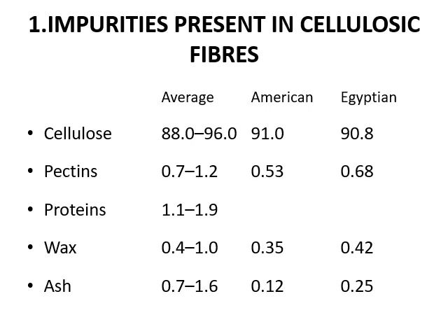Starch, usually esterified or etherified, is the most common size, but polyacrylates, cellulose ethers, that is carboxymethyl cellulose, then polyvinyl alcohols and polyvinyl acetates are also used. The source from which the starch is obtained, that is from corn or rice, can affect its ease of removal. Size plasticizers such as tallow or paraffin wax are either added to the sizing liquor or applied after the size has been dried onto the yarn by kiss roll coating.